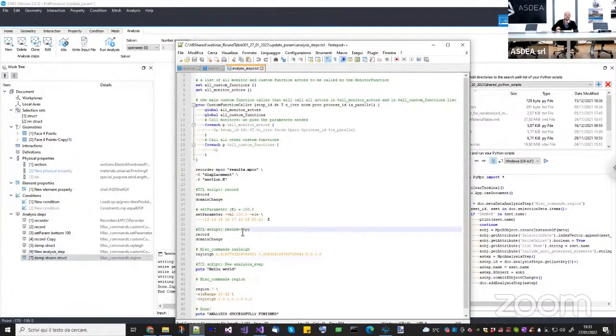And now, as you can see, you have your TCL script directly in between these two steps. Now, if you think about it, you will be able in this way to add new elements. The only problem is that if you want to add a new element like this, it should be in Tcl. It is very easy if this element is not connected to other elements in STKO. If it is, you still have some options, but it's quite complicated to explain now.